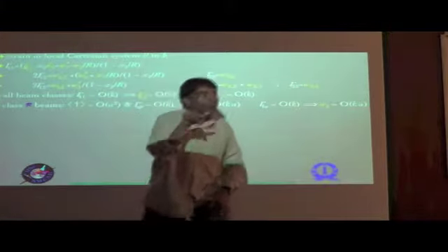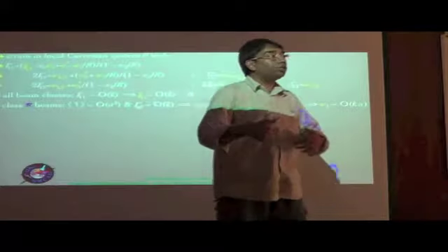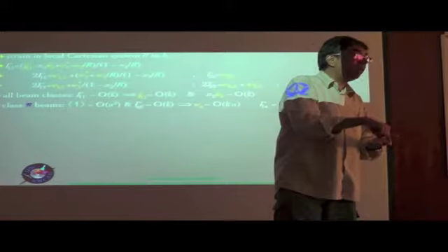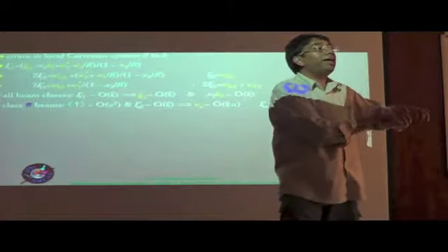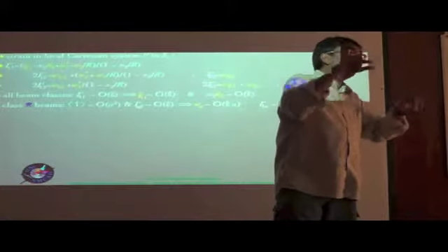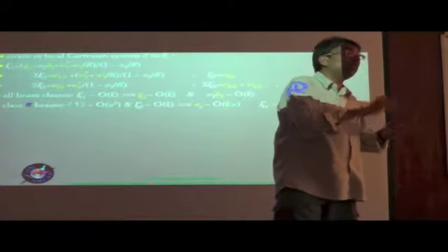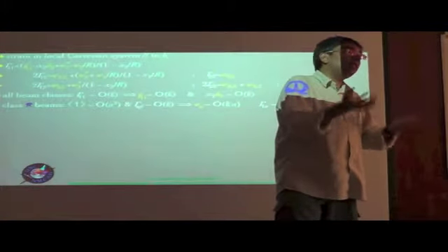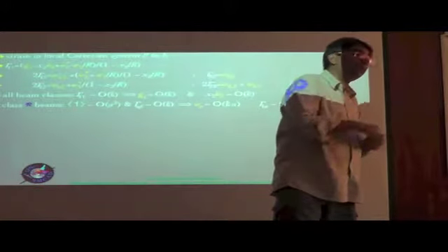On the other hand, the warpings and therefore the local rotations are all functions of gamma 1 bar, kappa 2 bar, and kappa 3 bar. So it is possible that the local rotation can act as a combination with one of those. Typically it is kappa 1 which will act as a combination with one of the local rotations to show that when kappa 1 is large, the corresponding local rotation can also be large, such that their sum would still be small, contributing to the corresponding strain measure, which should be a shear strain measure. Right?